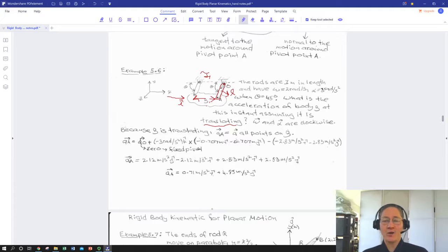And we're going to look at the motion of L with reference to our fixed reference frame, which is like the ceiling that these bars are bolted to, up where the hinges are. Okay, so our point that we know the acceleration of with respect to our fixed ceiling reference frame is O. It's the hinge. And the nice thing is, its acceleration versus the ceiling is 0 because it's bolted to the ceiling. It's the hinge. We drilled some holes and bolted it down. It has no acceleration versus the ceiling.